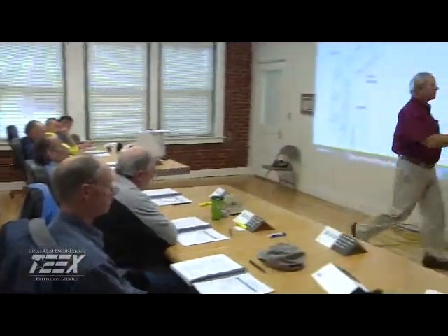Okay. And things like this. Texas, they recommend 30 to 60 minimum. Absolute minimum is 24. And then we talked about trench safety yesterday. Just remember, there's 3 classifications of soil, and then you have stable rock. Some people call it 4 classifications of soil. But you have stable rock, and remember the slope for stable rock is 0 to 0. You got to run to rise, and I'll put this up here again just for review.